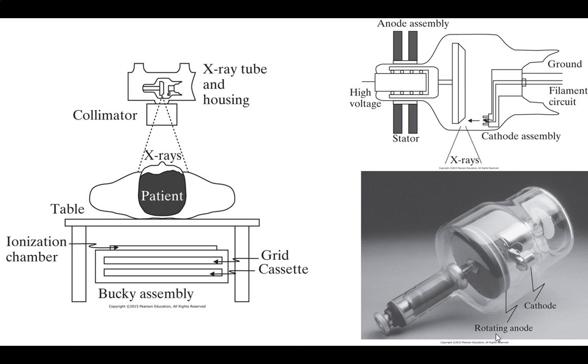As a result, what's going to happen to this? It's going to heat, right? If you have it constantly in one spot, it'll heat up too much and you've got a problem. So we make this really big disk so it can spread around. And then you just set the speed of rotation depending on how much you're sending down, so it can rotate and allow you to spread the generation of heat to different areas.